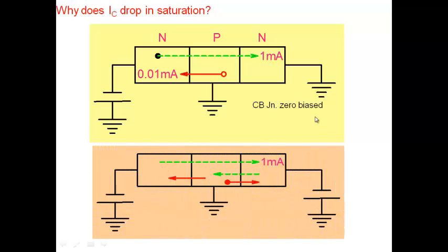So this is a description of a bipolar transistor. As usual, our base emitter junction is forward biased. So electrons are being injected here and holes are being injected here. And I've shown that this is, by the way, the direction in which electrons flow. The electron current would be opposite. Okay, so I've shown here that the electron current, let's say, is 1 milliamperes, and the base current, the holes that you see here, is 0.01 milliamperes here, just for the sake of discussion here.